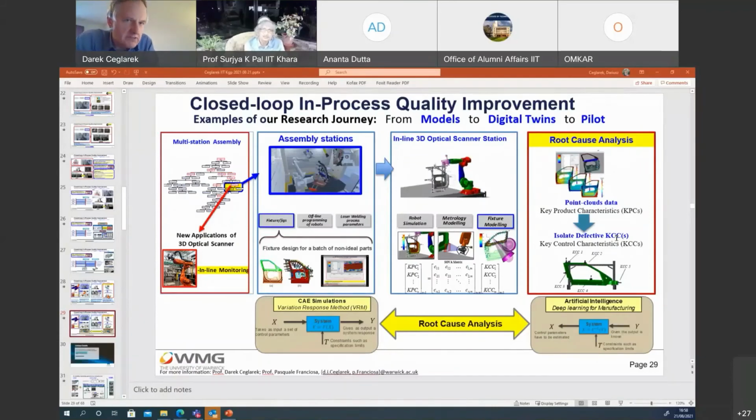Let's say pores, cracks, width, how wide the nugget is, if you're not familiar, and depth, penetration. Sometimes the shape is also important: concavity, convexity. So there are different requirements I just brought up for welding itself. Similar requirements come from dimensional or geometric tolerances, so we take those into consideration.